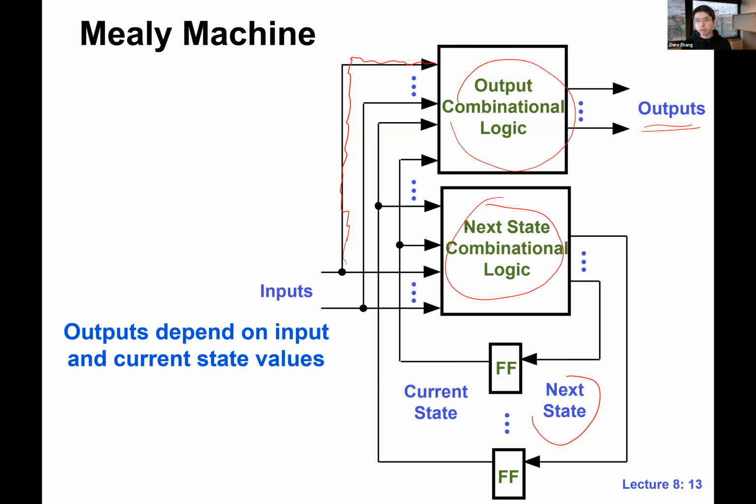So again, in Verilog, if you want to infer a flip-flop, you need to use a clock edge in the sensitivity list. If you want to specify conditional logic, you don't want to use a clock, but you want to make sure that under all conditions, the output is assigned. Otherwise, you have a latch.